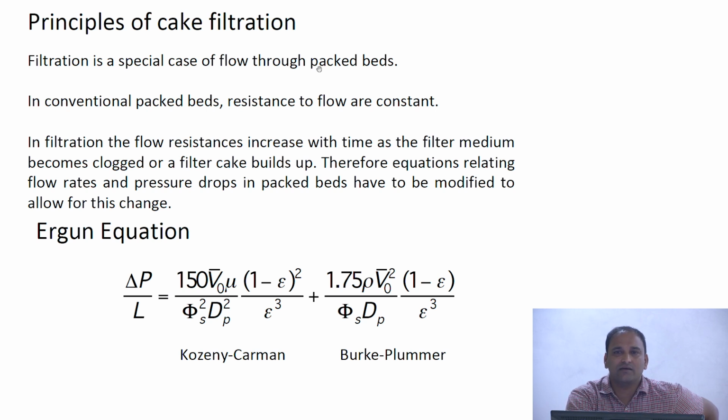The only thing is, in conventional packed beds, the resistance to flow remains constant. However, in the case of filtration, the resistance to flow changes during the course of your operation.